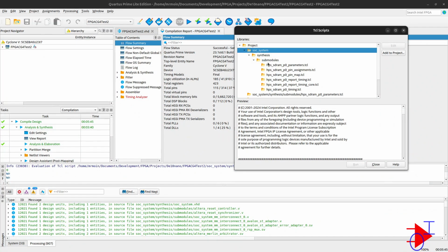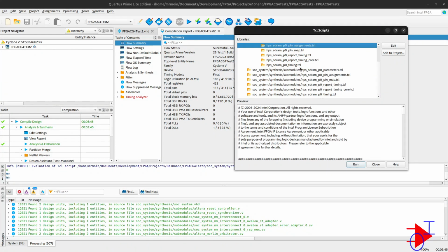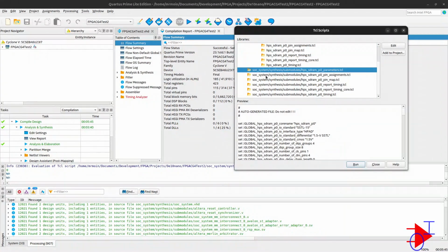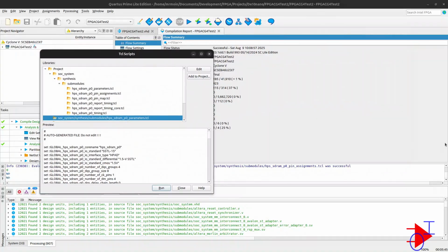It should show in your script window as structured, and if it's not showing in a structured format, then it is not going to complete the physical connections that the HPS needs to connect to the FPGA. So this is one big point you want to keep for your future projects, and I'll keep it for mine.